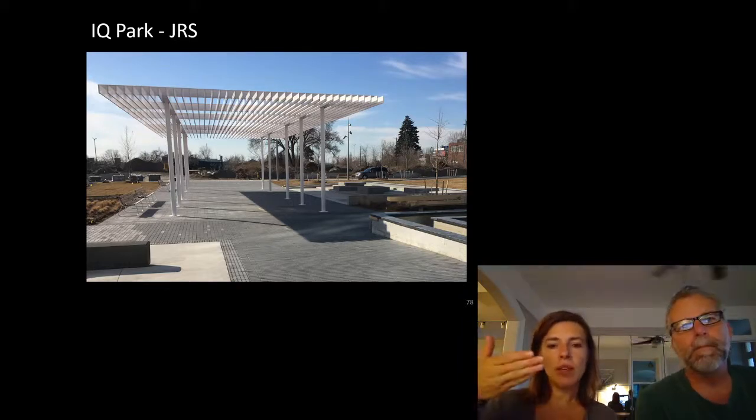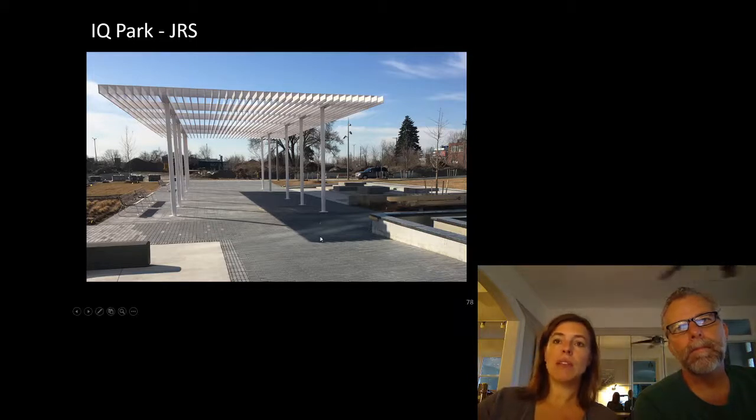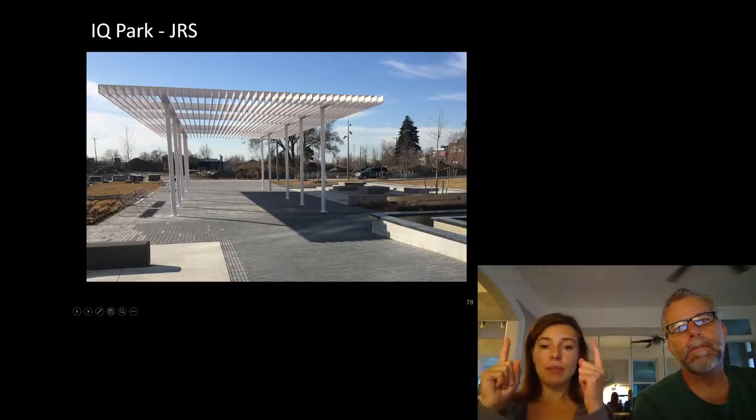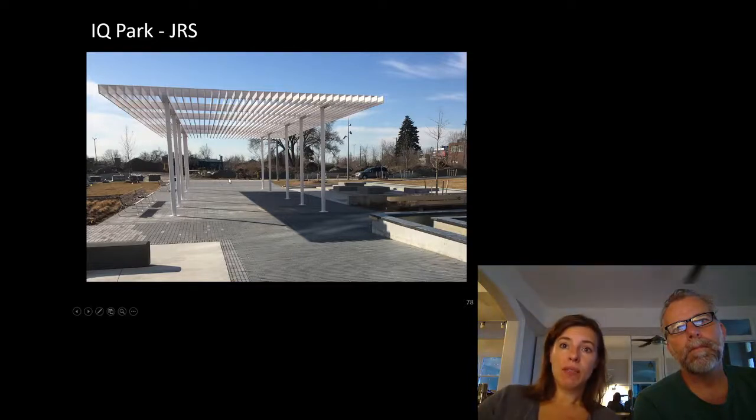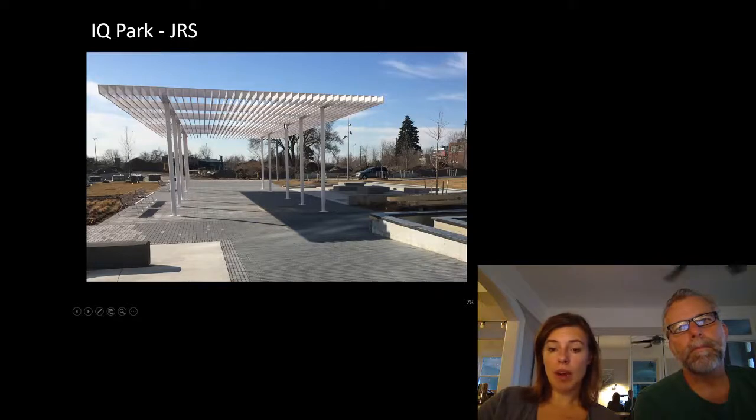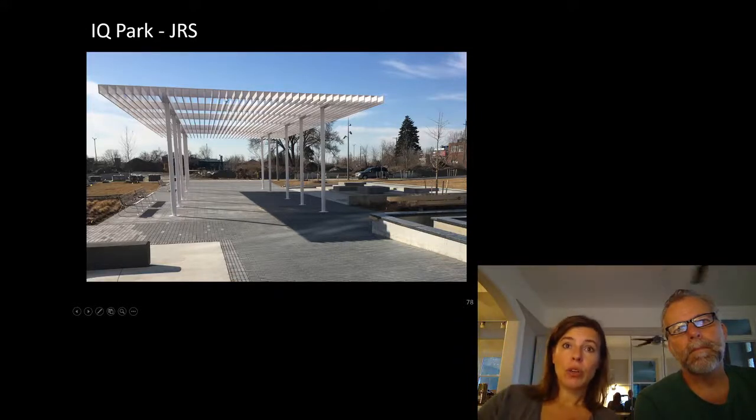I think in one direction it's a moment frame, and in one direction they're cantilevered. Yeah, so in this direction, they're moment frames, where we only have 2 columns. And in this direction, the columns themselves are cantilevered up because we have a series of 5 of them that can do the work. So the only thing going in that long direction are these aluminum mullions that are providing no fixity for the overall system. So essentially we have a series of 5 individual frames acting independently that needed to be stiff enough that if they acted independently too much, they could cause damage to those aluminum mullions.